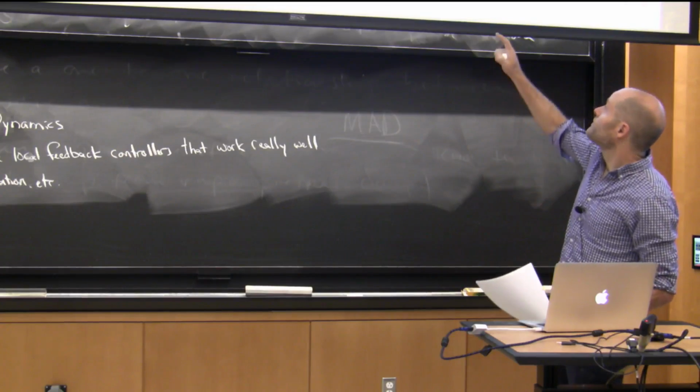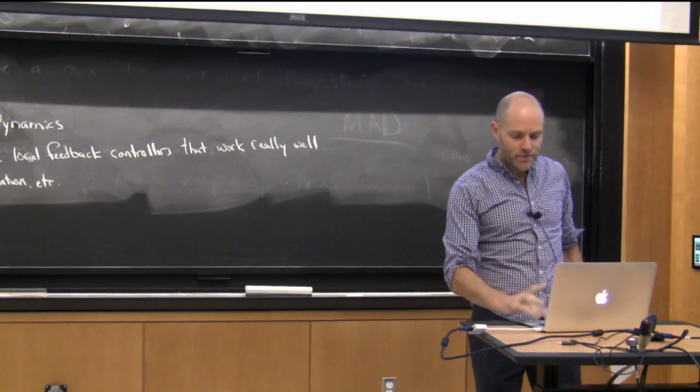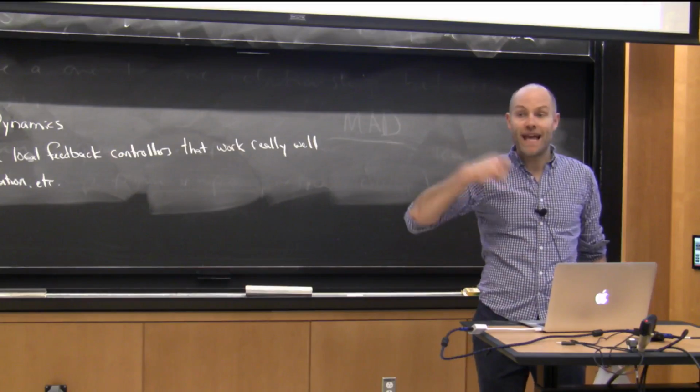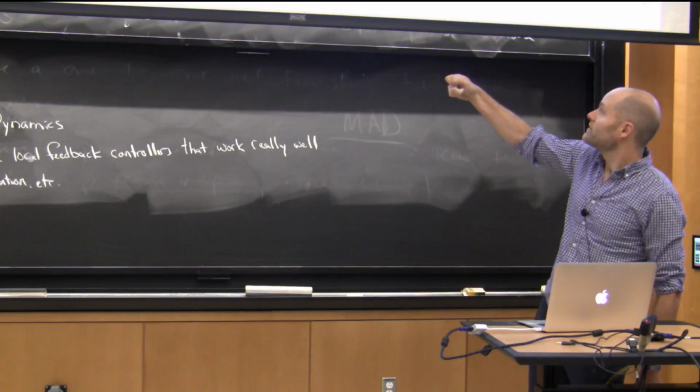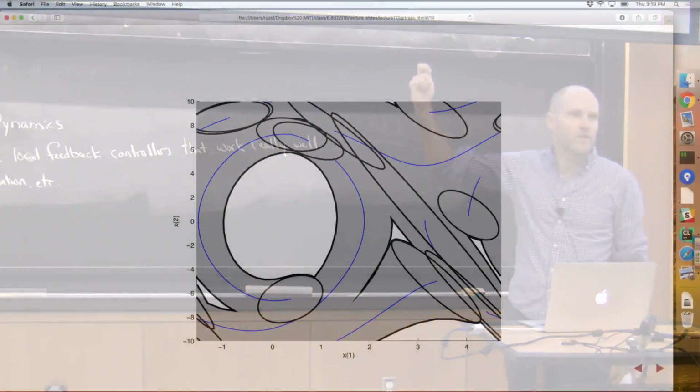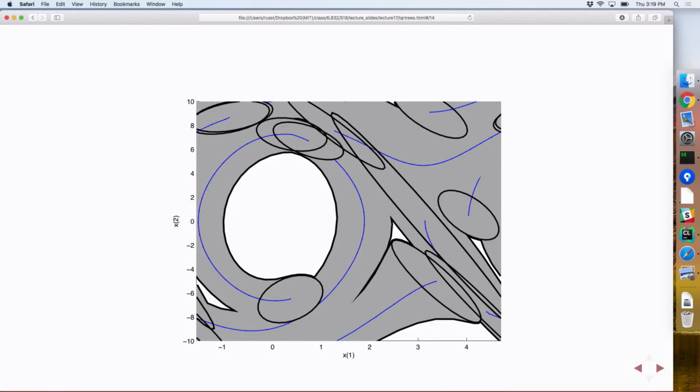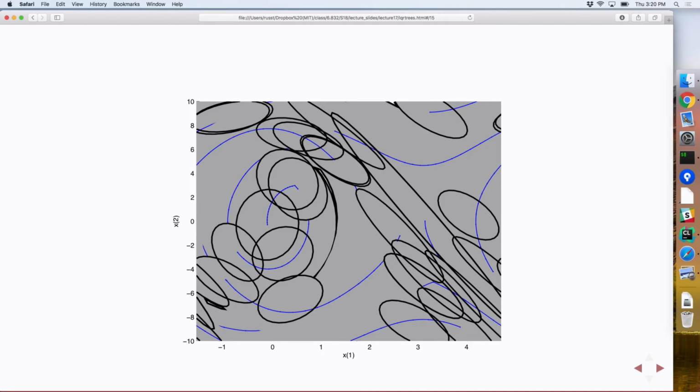Good question. Okay, now I'll sample again, discarding samples in any of the gray regions, right? And every time I get one, I add a new trajectory, add the LQR controller, fill the space, okay? Now we have a proposal which will take random initial conditions, specifically cover that initial condition with a local controller, and we'll eventually fill the space.